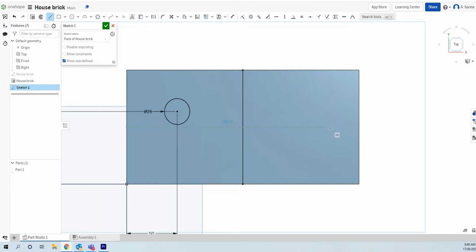As soon as I go off horizontal, it doesn't have that anymore. So make sure you've got that all the way along. Otherwise, when you mirror your circles, they won't be perfectly even. And when I go to the other side, you can see again, I get that little square that tells me I'm joining to the midpoint of that edge.